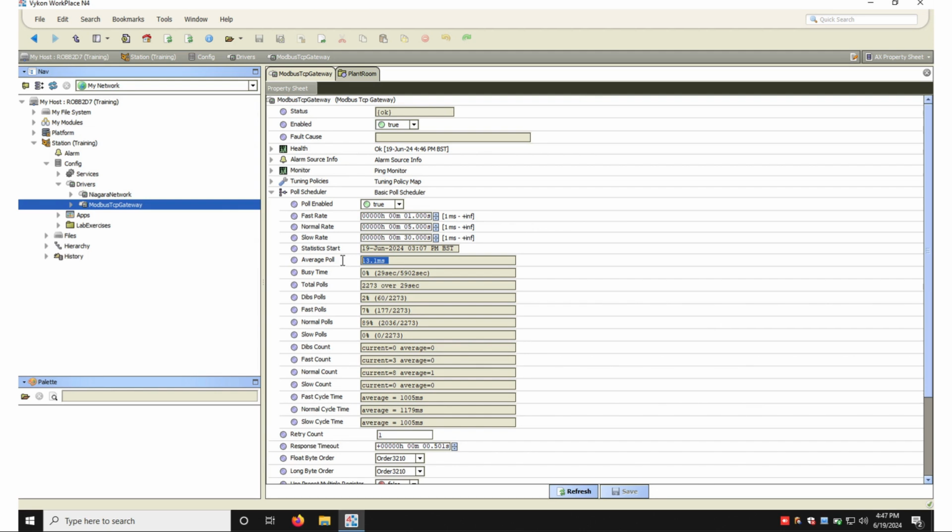The longer your network physically in length and the more devices you have, the slower that baud rate will probably be. If your devices are all local on a short, less than 20 meters network, you could increase that baud rate and go faster.